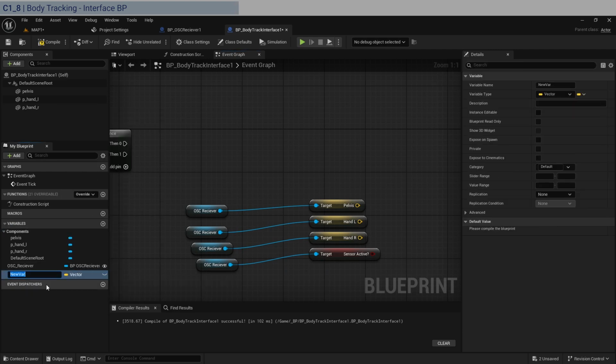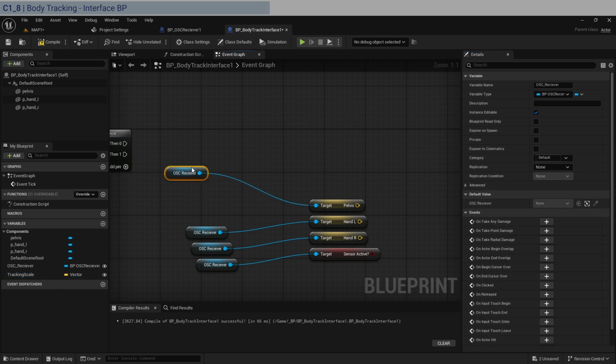And that's going to be the tracking scale. And we will expose that as well. Let's compile and give it a scale of 100. So why is it 100? Because when we go from Houdini to Unreal, to get the equivalent scale, it's 100x. That's the way we do it if we're doing an FBX export or import, sorry. And so we do that. And basically we do this.